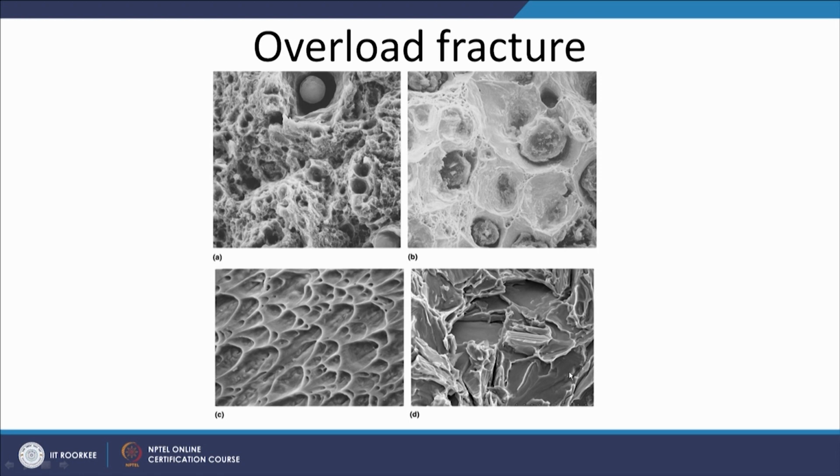So, this is the typical example of cleavage facets, where we can see the transgranular fracture, indicating the limited ductility and the limited toughness of the material.